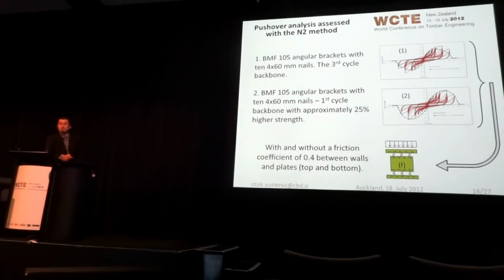Talking about rocking walls, if you are at the bottom of a 5-story building, there's a huge amount of gravity load coming down. So how do you expect the wall can rock? How much rocking are you expecting? Well, of course, it depends on the story height and the mass of the structure. But from the tests that were conducted, for example, at my faculty almost 6 years ago, even for very high loads on walls, of course you have to take into account as well that a wall can only take so much vertical load before the wall buckles.